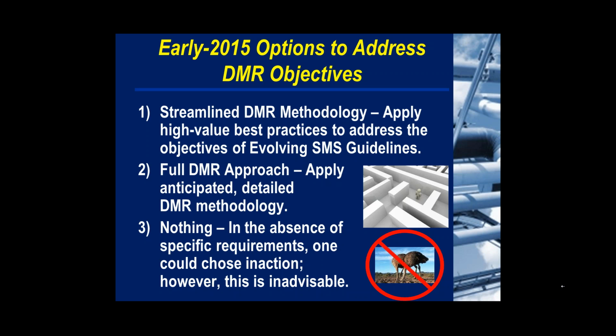The concerns identified for the August 6, 2012 event are long-term sulfidation corrosion, deficiencies in the metallurgy, and maybe some criticism of where the focus of the inspections was. The sulfidation corrosion mechanism was a known issue, and there were decisions made about when to fix the problem or replace the piping segment, and there was some criticism about when those actions were taken.